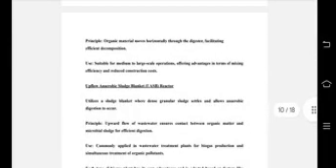Types. Continuous stirred tank reactor is there. Then batch or semi-batch biogas plant. Then plug flow biogas plant, the plug flow system. Organic material moves through the digester in a linear manner with varying stages of decomposition along the reactor length. And then balloon biogas plant where a flexible membrane is there which fills with the production of this biogas. Then fixed dome biogas plant, horizontal plug flow biogas plant, then upflow anaerobic sludge blanket reactor, which is used in case of wastewater treatment.